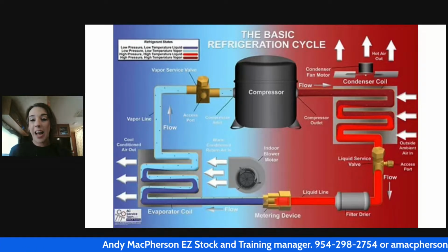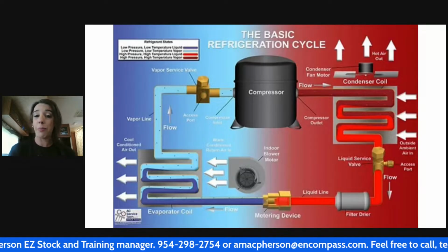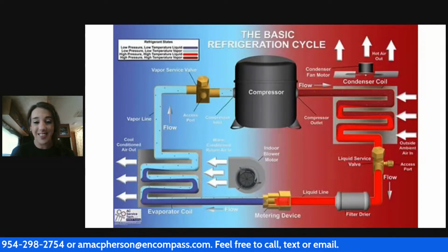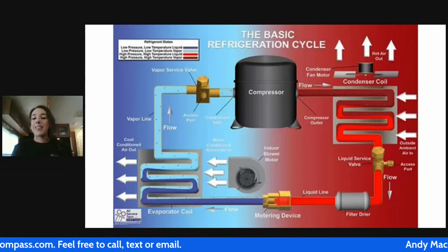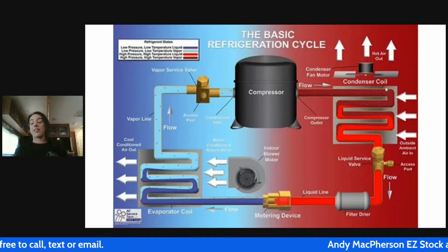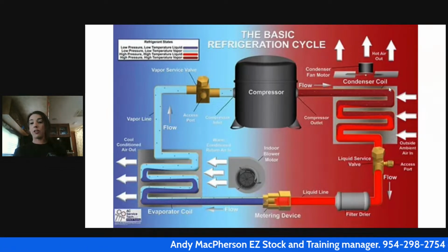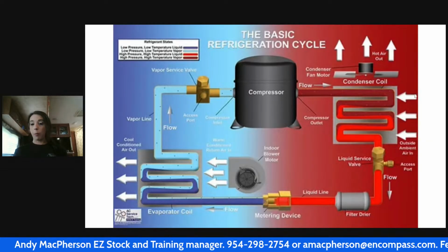Now there's other things happening. We can definitely move some heat with this process. But we can move a whole lot more if we add some fans into the ordeal, if we take care of our airflow, right? So what's happening as far as airflow goes is the condenser fan is spinning, the motor is spinning, the fan is rejecting heat, it's taking all of that heat out of the refrigerant that we have now turned into a liquid.